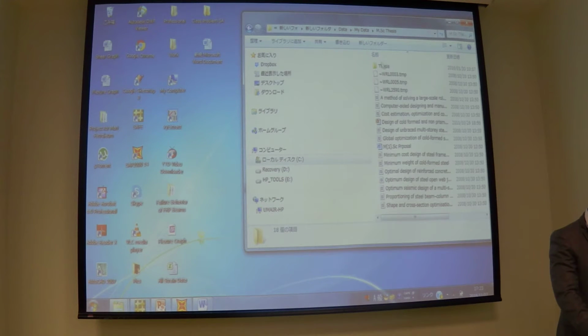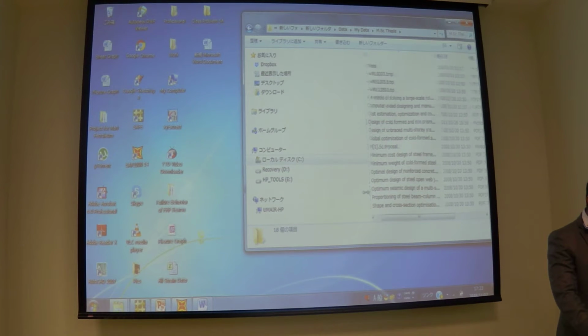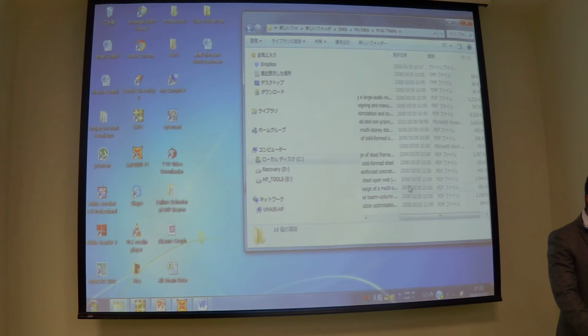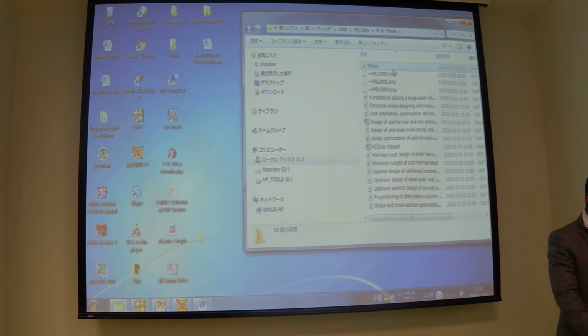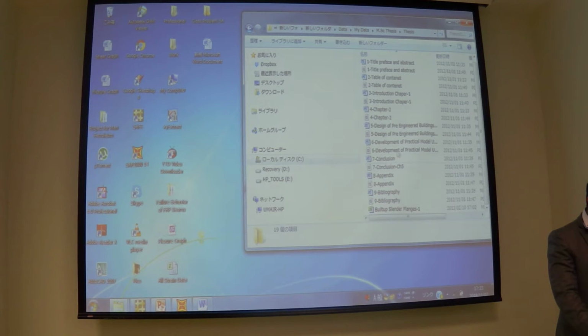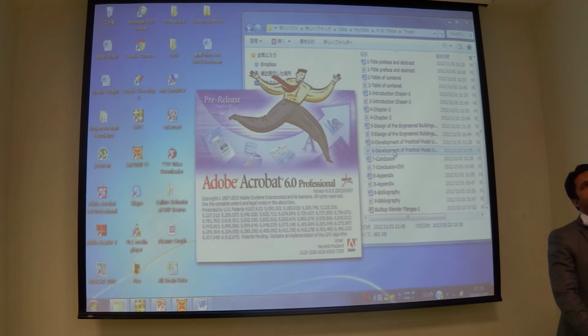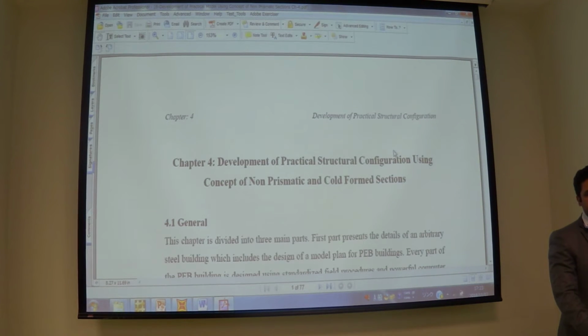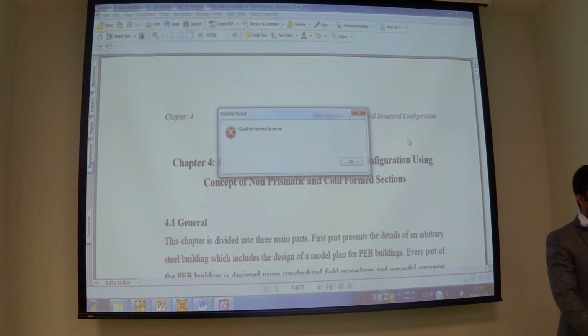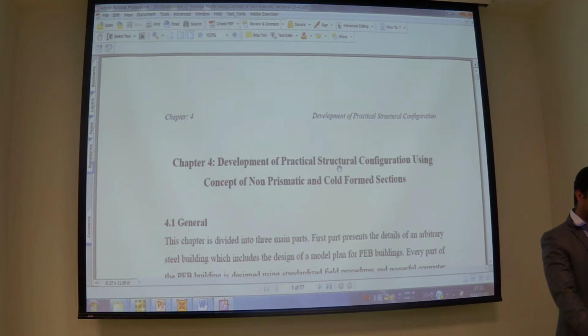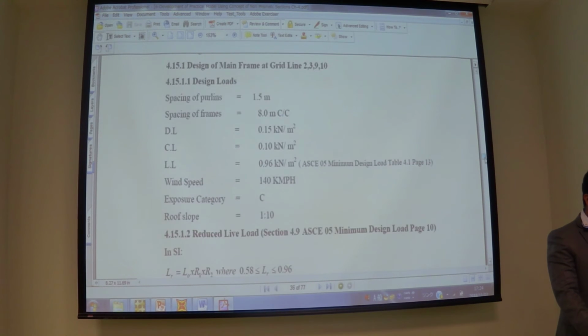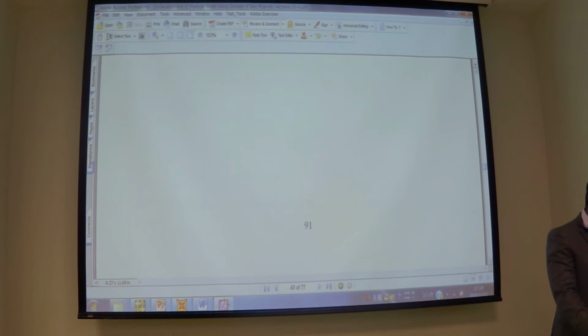Teacher, the factor of safety in your design is like 1.2. In my design, the factor of safety for steel is higher than that. It depends upon the code. For example, if you are talking about LRFD, it is dead load 1.2 and live load 1.6. But if you are using the other way, we reduce the material strength. Let me show you some of my design unity checks.